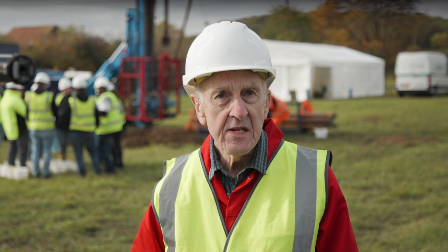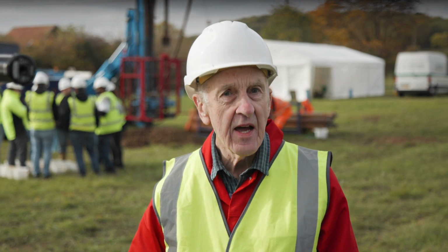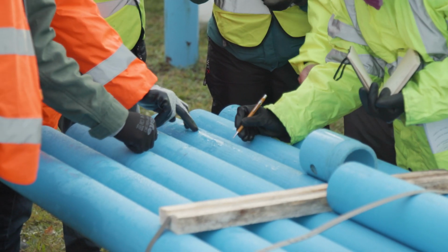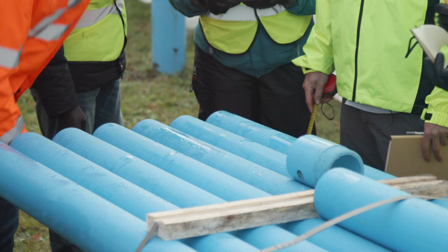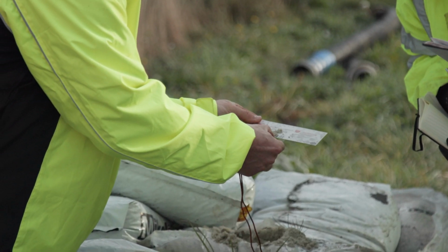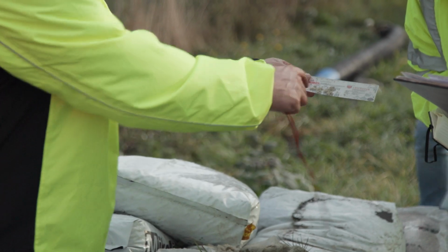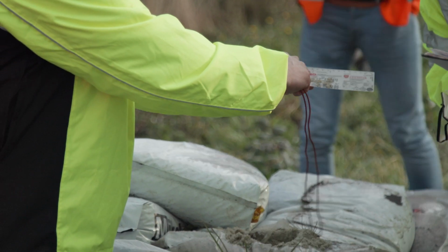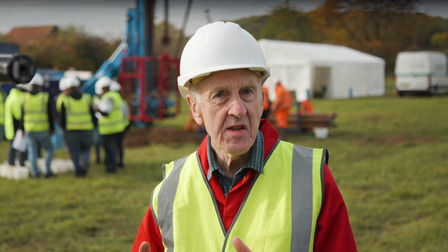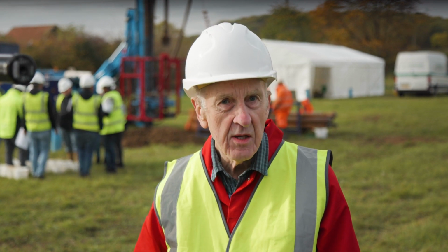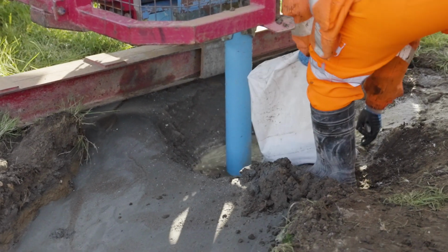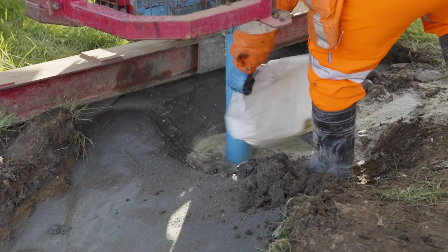Well lining materials and materials for filling the annular space need to be assembled. The sump, the casings and the screens need to be measured and placed in the correct order. The permeable backfill and the sanitary seal materials need to be checked. Quantities of backfill materials need to be estimated, recognizing that some collapse of the hole may occur, which reduces the annular volume, or that the hole volume may be larger than expected.